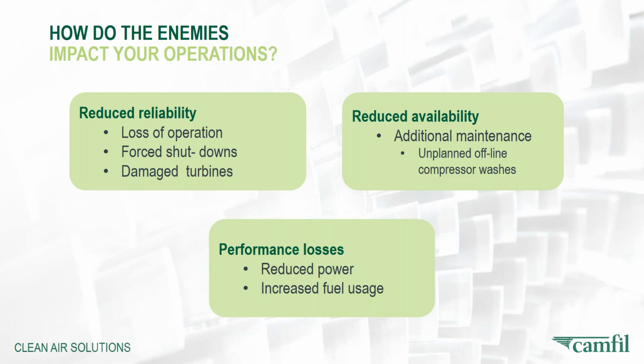The second impact would be related to availability of your machine. And that's where you have unplanned or additional maintenance. Perhaps it's due to unscheduled offline compressor washes. And the third impact would be related to performance losses, a reduction in power and an increase in fuel.